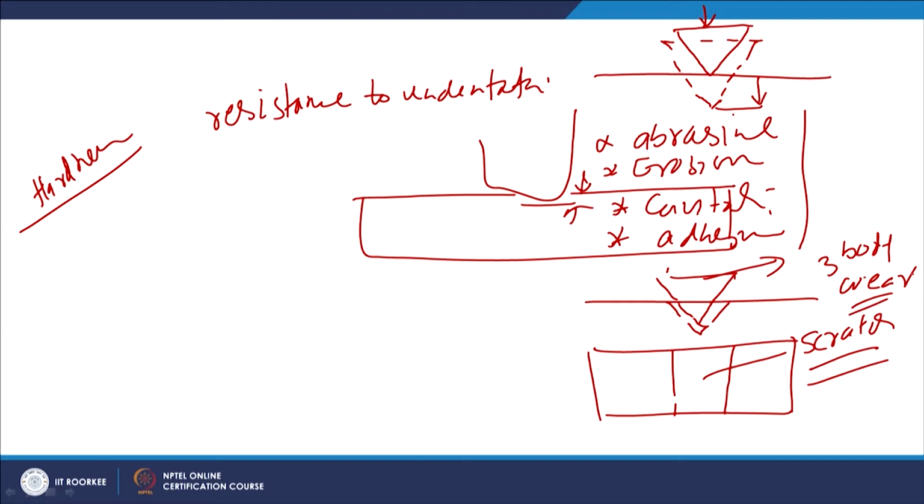Similarly, under the cavitation conditions, when a bubble bursts, the bursting of the bubble develops pressure, and these pressure waves hit the surface. So, it will cause surface layer deformation.